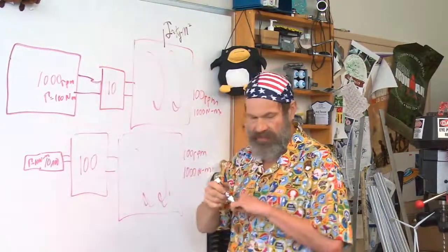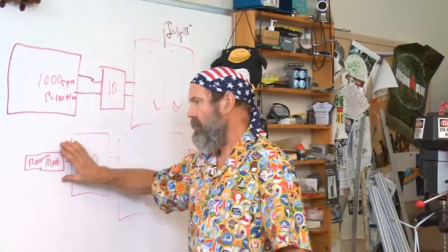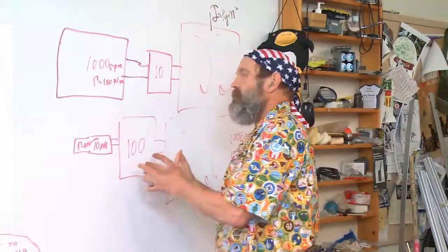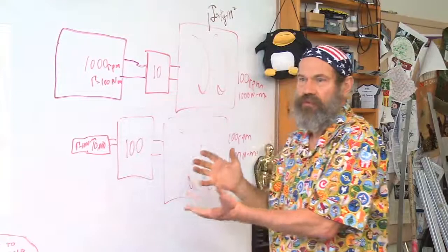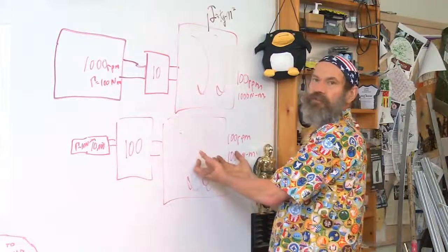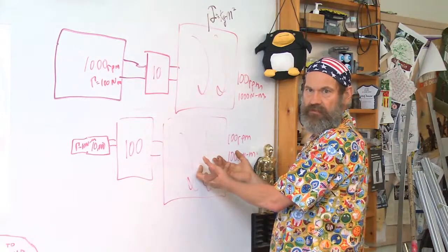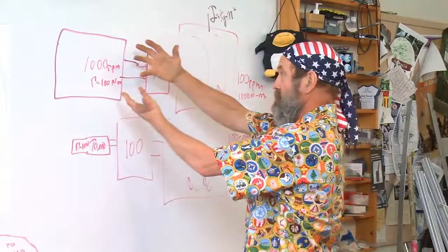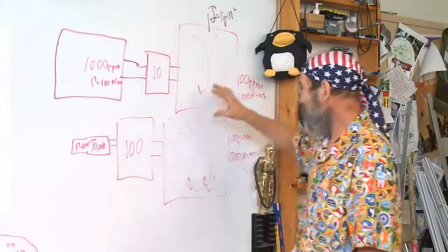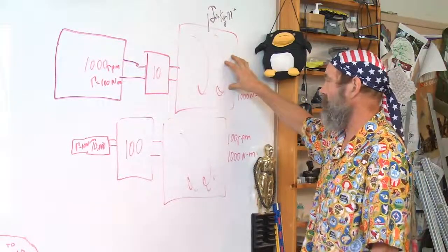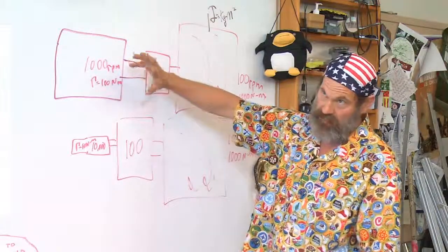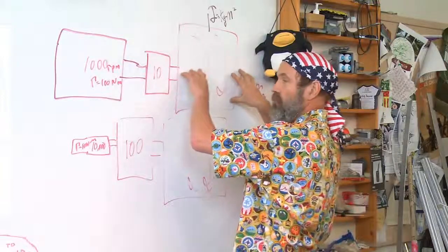What we're saying here is, if you have a little motor that goes really fast, you spend so much oomph spinning up your motor that there's very little oomph left to spin up your mass. If you've got this great big, high torque, lower speed motor, well, this has such a large inertia, it's not getting up to speed in accordance with the load either.